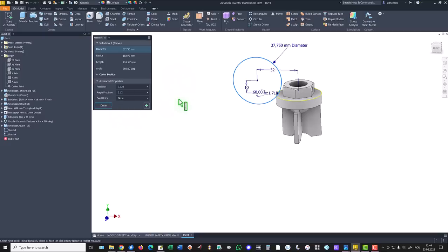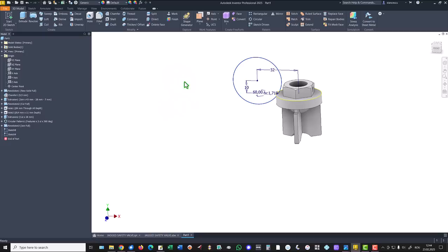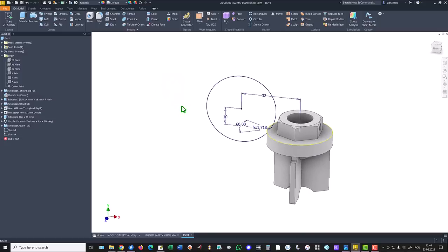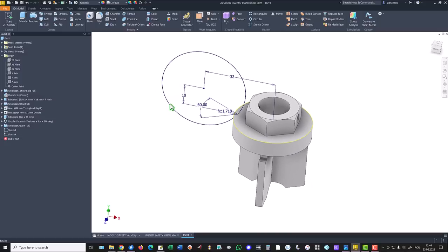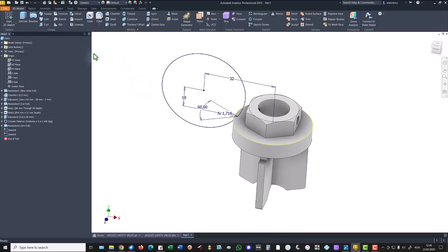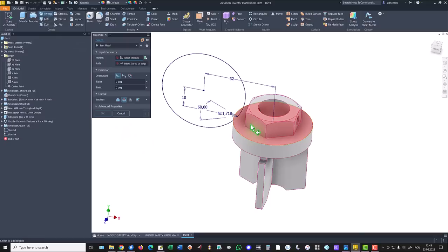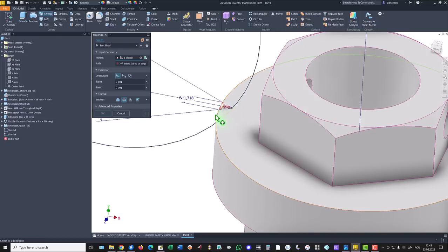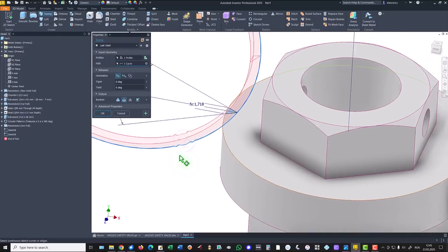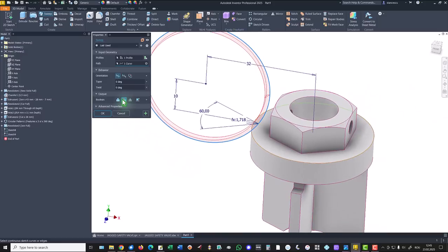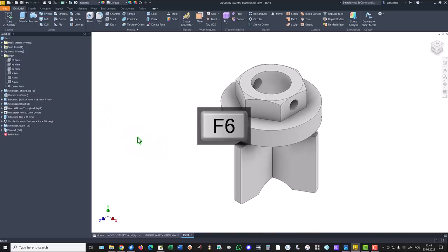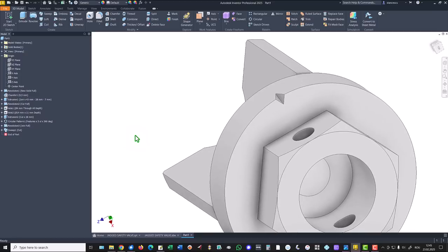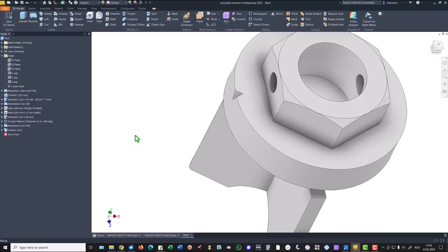We don't need it at all, because all we have to do now is to apply sweep of this area about this full circle with cut, not join, but cut. Okay, you see the notch.